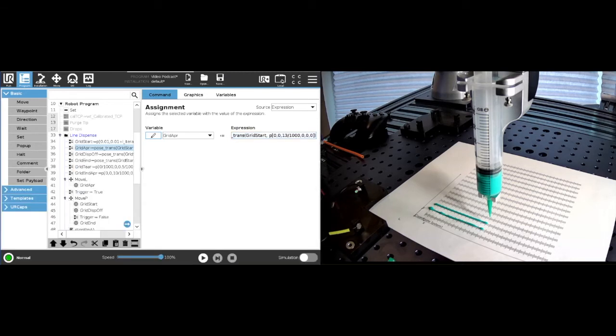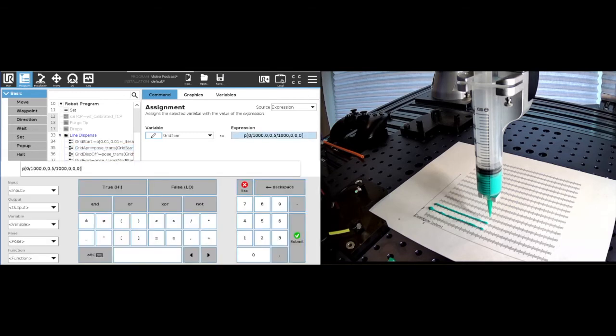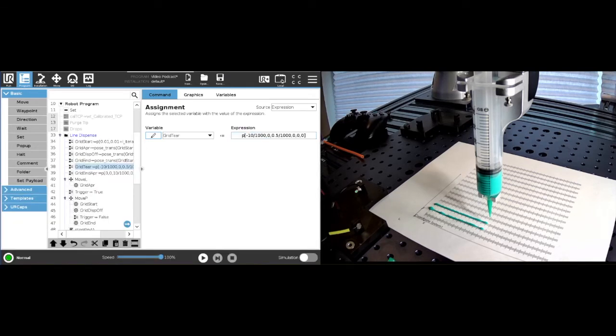On that back end, something I may want to do is, when we finish, come back in the direction of the line so that we put this blob right at the point where we turned off. So this is where this grid tear might come in. We might want to come back, let's say, 10 millimeters in the X direction, so that we fill that little space where we started to turn off. So we run this again.